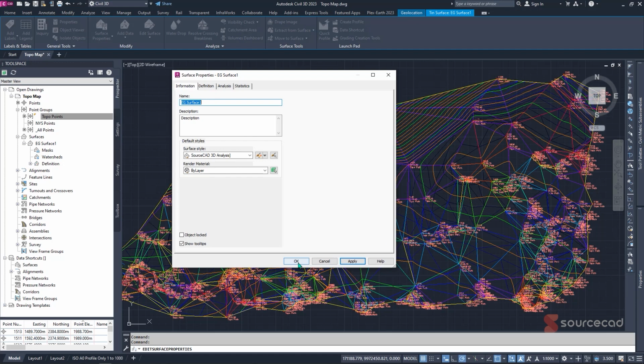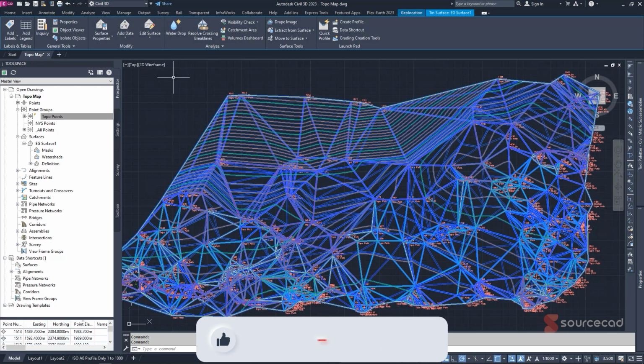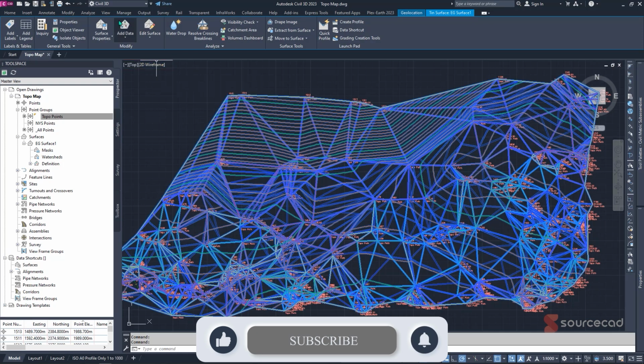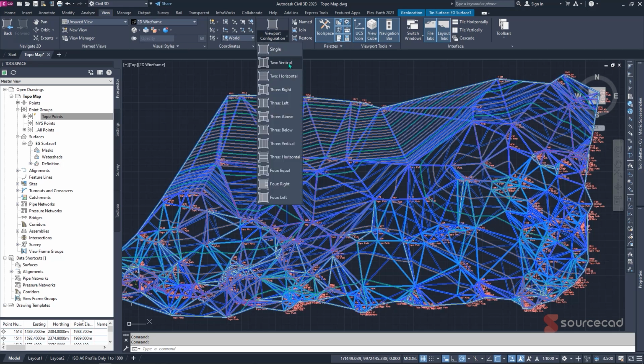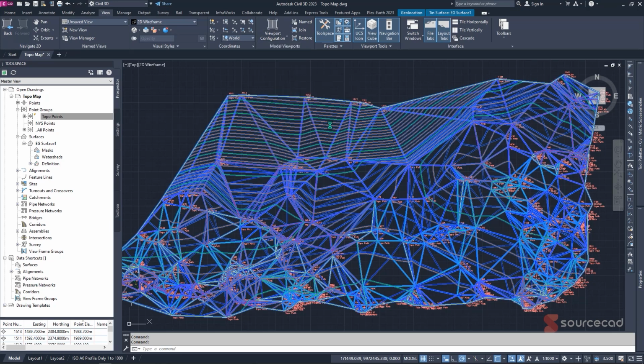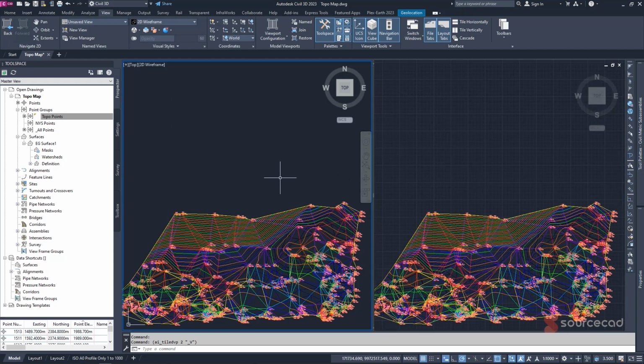So right now we have this thing looking like so. You're wondering how it looks like, but it's because we are in the wireframe. But to change the way you view it is quite easy. You can just simply go to view here, and you can even change the number of viewports that you have. So let's say we want to have 2 vertical viewports, so one on either side, something of the sort. So we can have one on this side and the other one on this side.